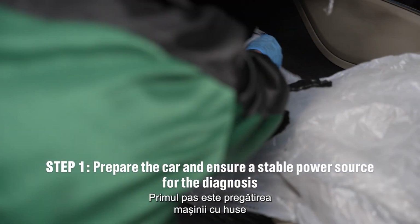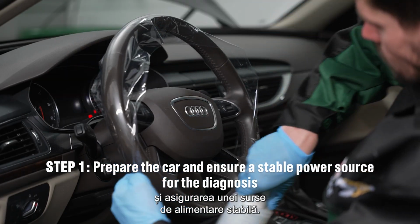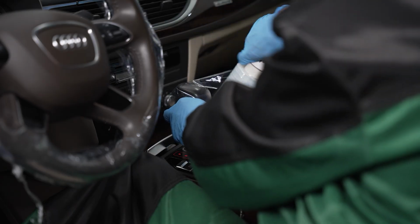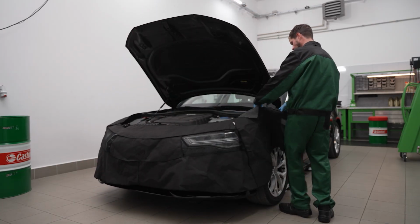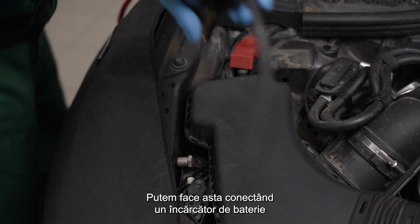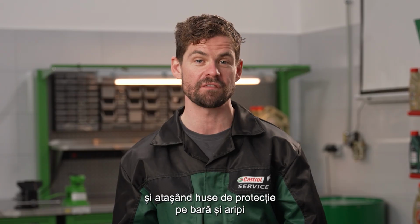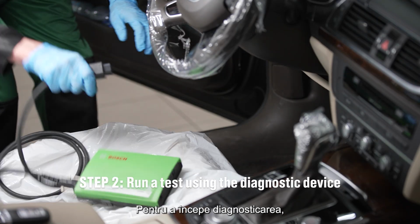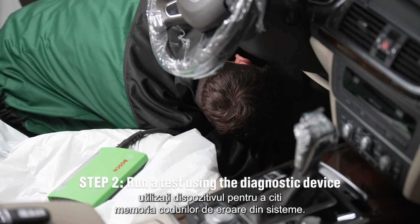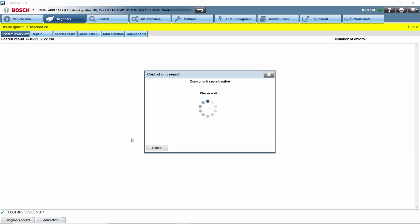The first step is to prepare the car with covers and ensure a stable power source for the vehicle. We can do this by connecting a battery charger and attaching the protective covers to the fenders for the duration of the diagnosis. To get started with the diagnosis, use your diagnostic device to read the error code memory of all vehicle systems.